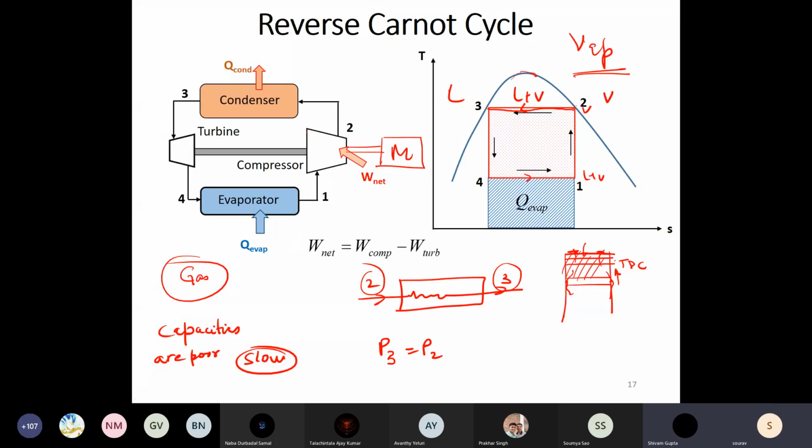They will not have such a large change in volume. So probably the piston will displace from this point to only this point. And within this small change in volume, the pressure would be so large that the discharge valve will open and it will pump the water to the higher pressure. Whereas a gaseous compressor is made to work with very small clearance volumes.